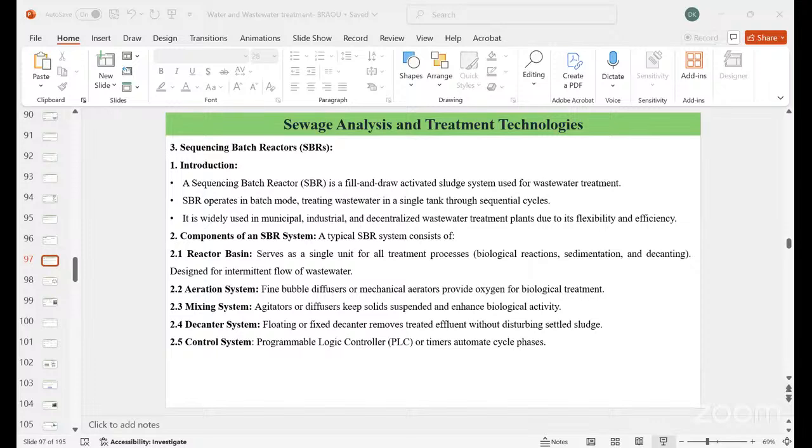So preliminary and primary treatment should be done in order to go for the disinfection process. The lower the turbidity, the higher the treatment efficiency of the UV process, for effective penetration of the UV light. Other disadvantages are no residual disinfection, and it can be energy intensive.